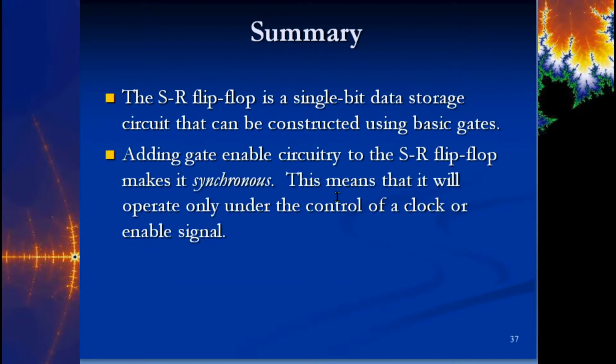Let's go ahead and just review real quick. So the SR flip-flop is a single-bit data storage circuit that can be used constructing basic gates if you would like. Adding gate-enabled circuitry makes it synchronous, so you need to know those two terms, asynchronous versus synchronous. And it says that means it will operate only under the control of a clock or, and this is a big or, an enable signal.